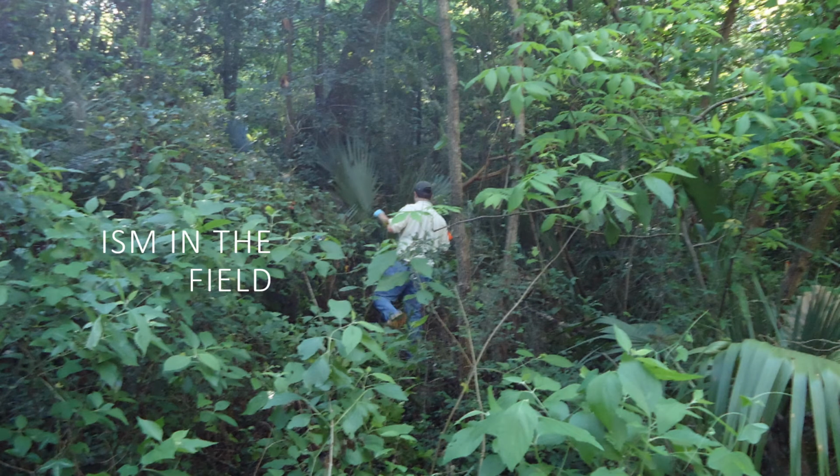But laying out a sample grid physically in space is a luxury that cannot be afforded at some locations. At some sites, it is just not going to be possible or practical to lay out a sample grid or place the markers for increment locations. In these cases, alternative methods will be needed to keep track of the team's location within the DU and the approximate location of each sample grid and each increment location. In this case, flagged wooden stakes were used to mark the corners of the decision units. The location of the next sample was paced off as the sampler made his way through the brush. GPS was of limited value due to the dense vegetation. Things could be measured off with a tape, etc., but things were difficult.